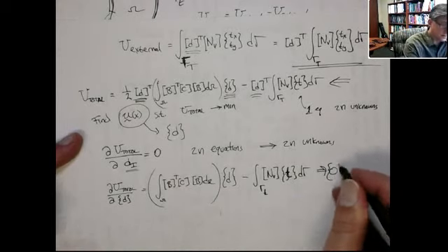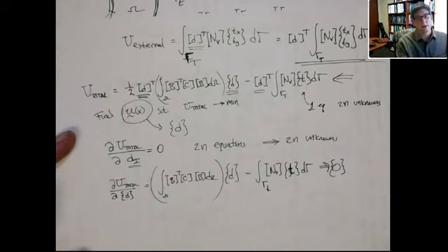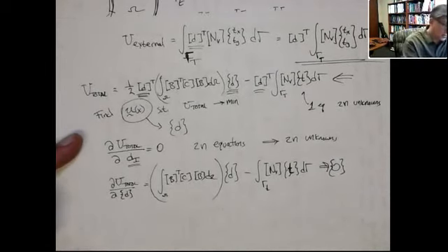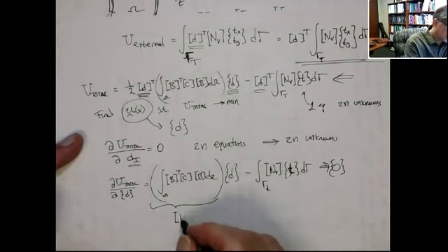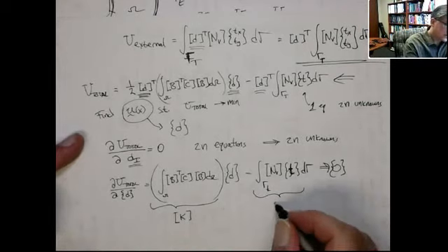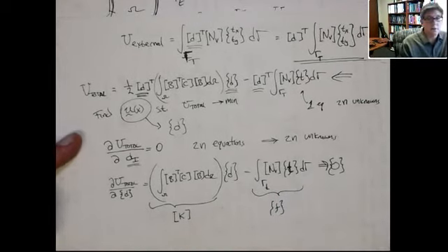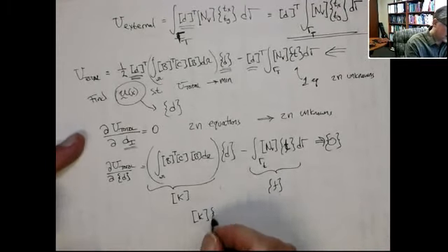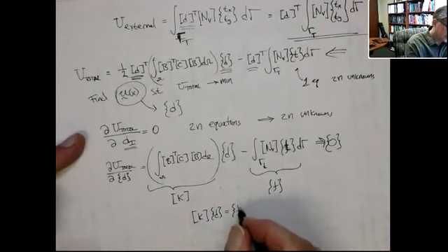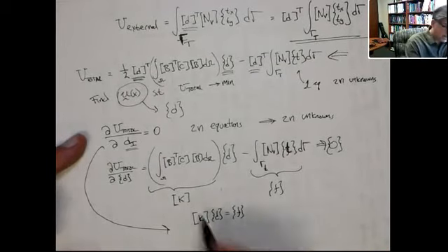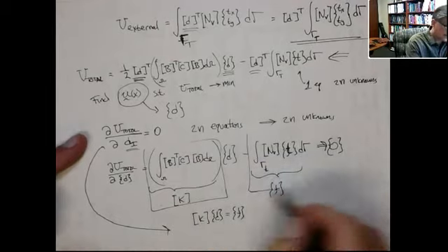And this we're going to set equal to 0. Actually, I should put braces around that because it's not the null set, it's a 0 column vector, all right? And now if you look at this, this looks something like where a stiffness matrix should go. This term here is the external force vector, and now this gives me K times D equals F. So this minimization gives me KD equals F, where K is defined as follows and F is defined as follows.